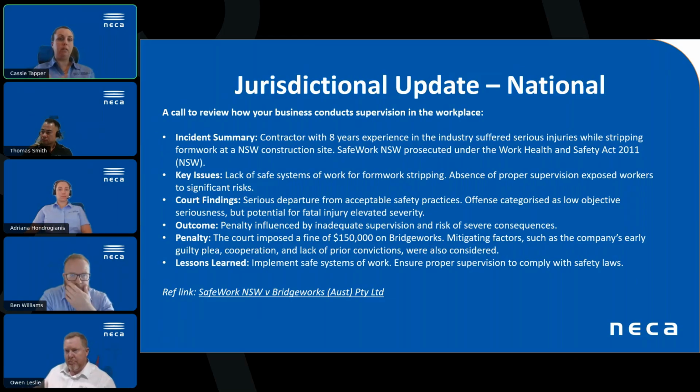For this case, summary of the incident: we had a contractor with 8 years experience in the industry. They suffered serious injuries while they were stripping formwork at a New South Wales construction site. So they were prosecuted under the Work Health and Safety Act. Now, the key issues that were found was that there was a lack of safe systems of formwork for stripping and an absence of proper supervision that exposed workers to significant risks.